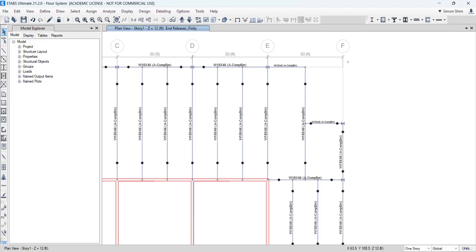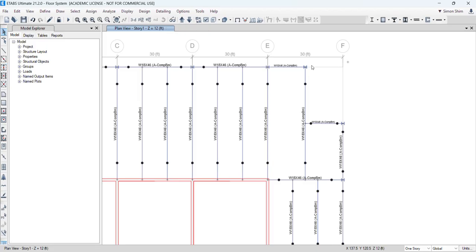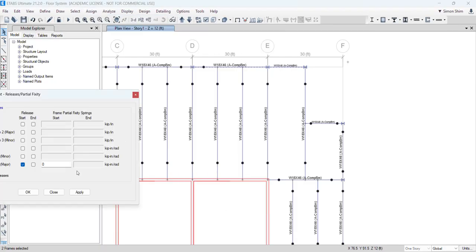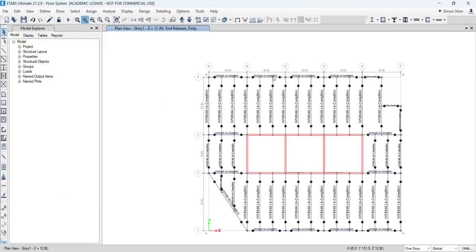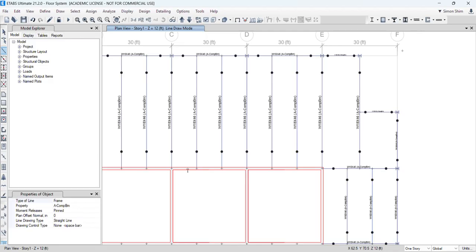It depends on your kind of structural planning. If we have a column, it's no issue. I'll just make this all moment release, simply supported, right? So this is normal framing, right? All right, but this might be a little bit too long. Worst case, I'm going to add one more composite beam here in the middle point.